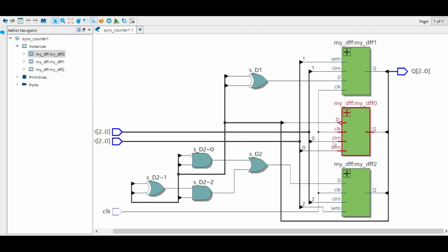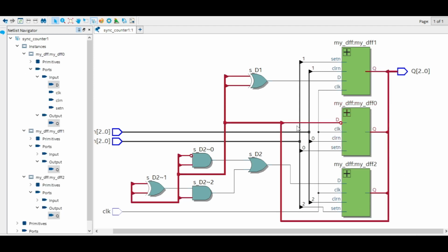But then notice that what you have is a thick wire over here, and this wire that goes into your D flip-flop is thinner. It's significantly thinner because it's just taking one of them. You have your bubble here saying it is inverting that signal. So if you just look at this, apparently it is doing exactly what we told it to do. You have your XOR gates, your AND gates, OR gates, and it's doing exactly what we told it to do, and that is fine.